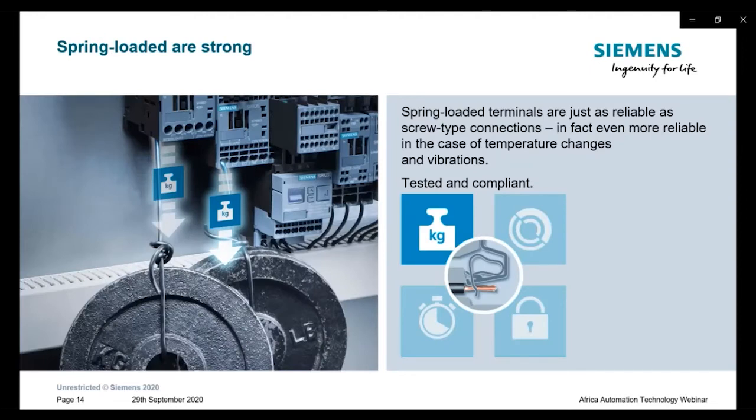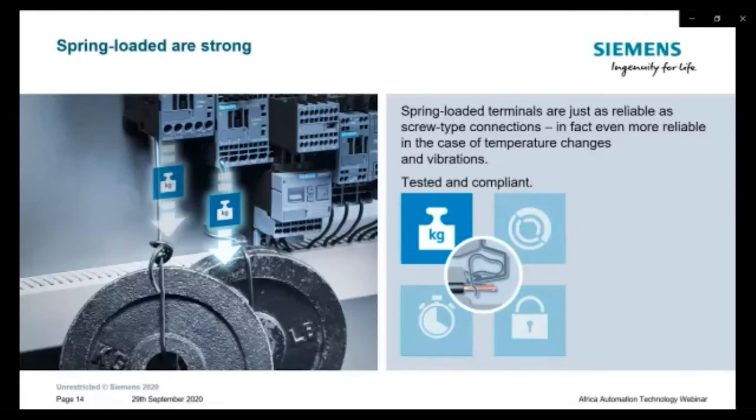Spring-loaded terminals are just as reliable as screw-type connections. In fact, even more reliable in case of temperature changes and vibrations, because unlike screw terminals, they do not loosen. This has been tested in accordance with the directives and international standards.